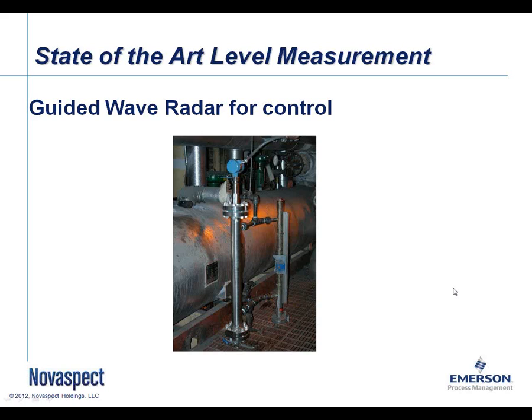So it's not going to work well in many of the high pressure steam applications, but it is proving to be very reliable on these lower pressures. This particular application that we're showing a photograph of here is a similar application, a steam blanketed heat exchanger, so that we have the same level measurement challenge that we see in a steam drum.